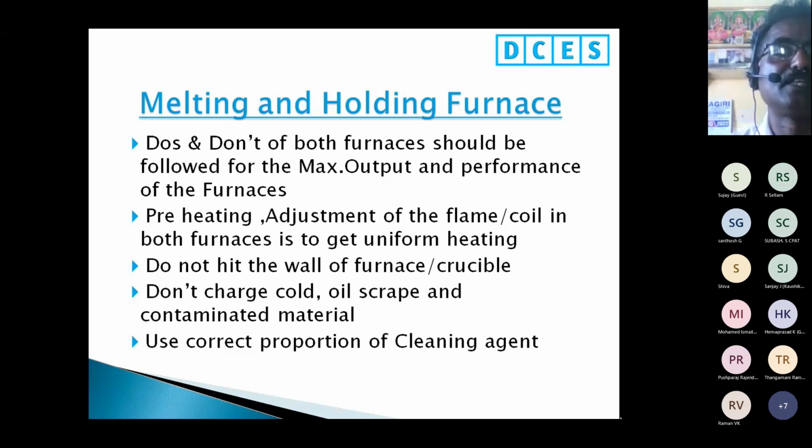What are all the don'ts? For example, when the operator is cleaning the holding furnace, they normally hit the crucible and the furnace wall harshly. It will damage them. That's why they should be properly trained. Preheating and adjustment of the flame or the coil in both furnaces is needed to get uniform heating, so the proper adjustment.